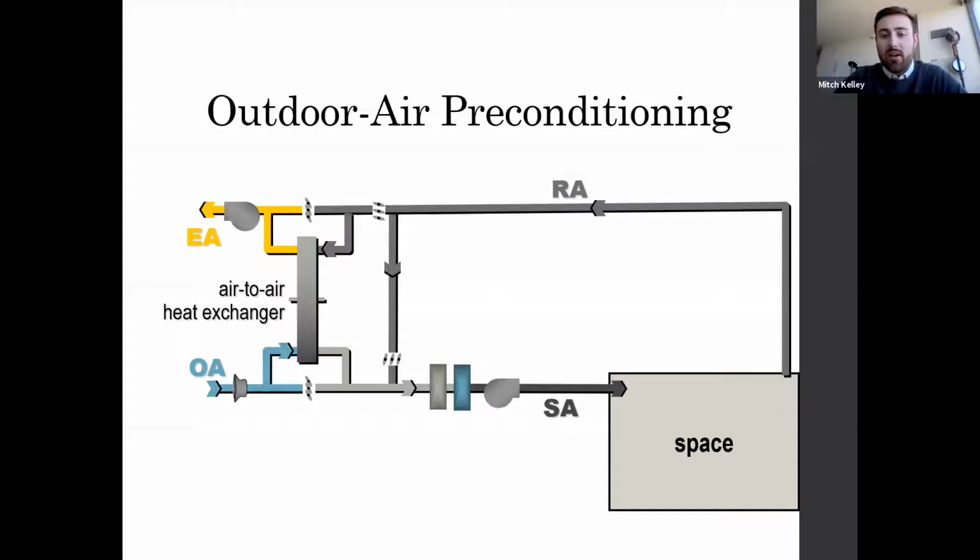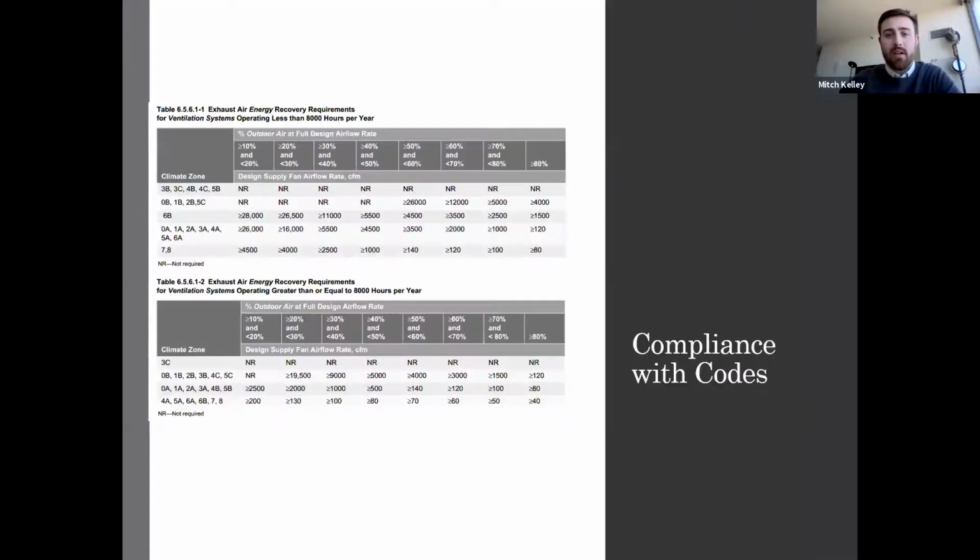The illustration shown here shows an air-to-air energy recovery device being used to precondition the outdoor air system. Air-to-air energy recovery refers to the transfer of sensible heat, or sensible and moisture, between two or more air streams, or between two or more locations within the same airstream. When it's hot outdoors, energy from the outdoor air can be rejected to the cooler exhaust air. But when it is cold outdoors, energy can be recovered from the warmer exhaust air and transferred to preheat the outdoor air.